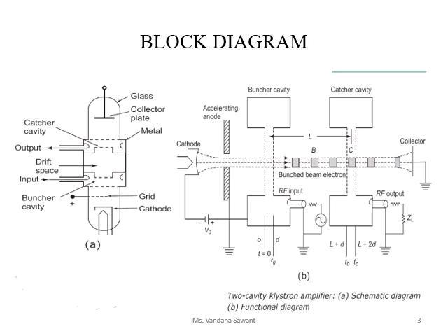The width is kept very small, and the electrons coming in contact with this RF field get accelerated and decelerated. In the first cycle they get accelerated and in the second cycle they get decelerated. This acceleration and deceleration of the electrons means that velocity modulation takes place. Due to acceleration the velocity increases, and due to deceleration the velocity decreases. As I explained in my previous video, as a result of this velocity modulation, when the electrons travel some distance they will meet at one point. Initially the distribution of electrons is uniform, but when they meet at one point the distribution changes, and that results in density modulation.